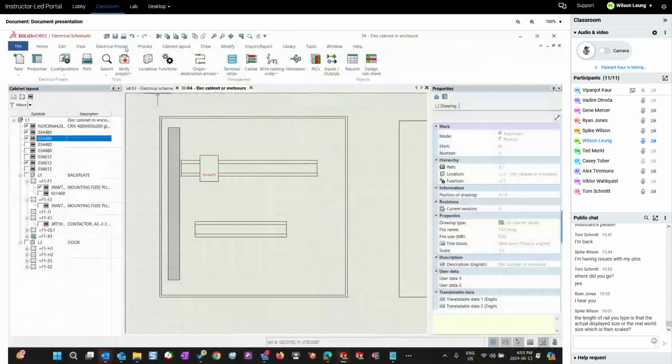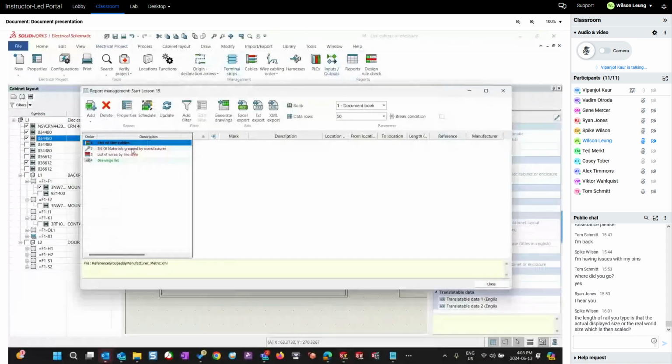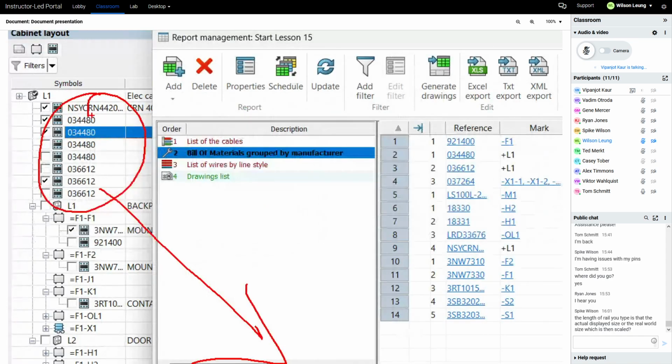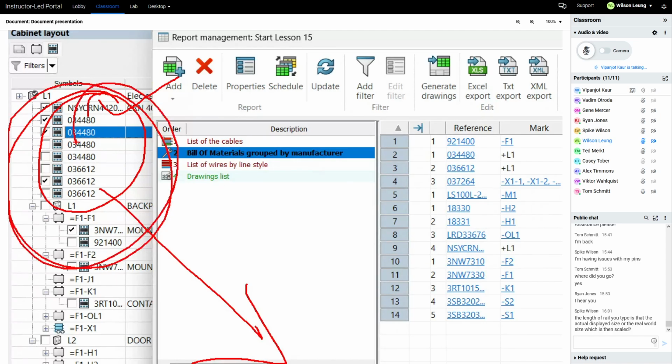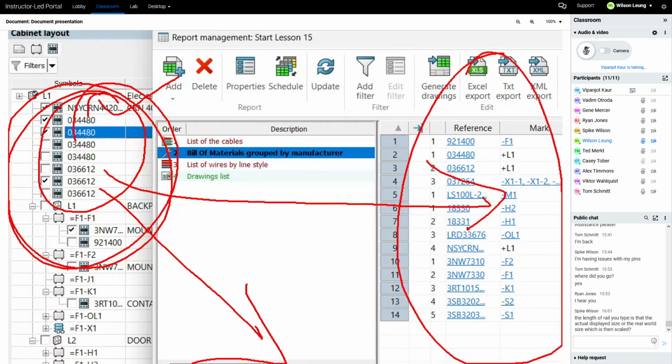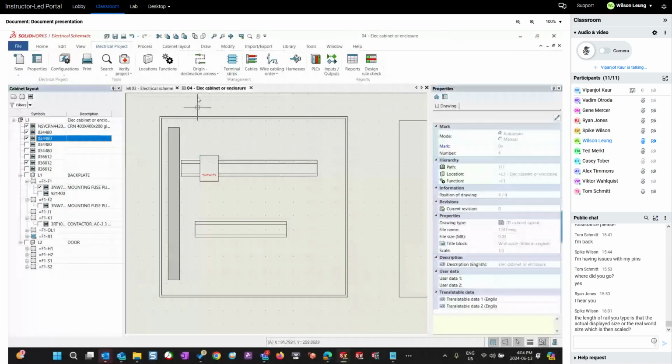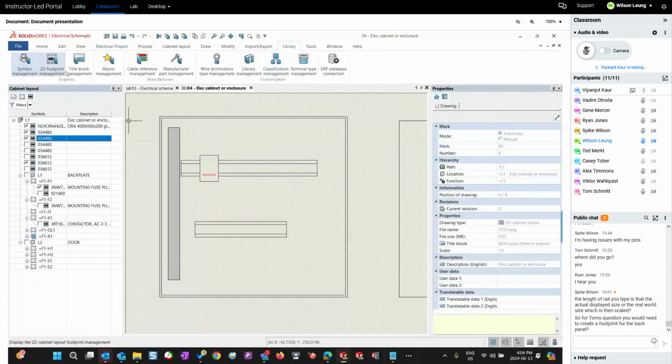And if you add a back panel separately, if you're placing an order for it separately, then yes, you would be adding it manually here, then showing it manually. If you're telling me, VIP, for example, for the door, I'm not placing a separate order for the door. It's coming with the cabinet. So I'm not showing the door separately in this list because anything I see here will show up in my bill of material list. And then Victor's going to say, hey, Tom, the back panel is coming with your cabinet. Why are you ordering it separately? So it's up to you. What do you want? If you want to order it separately, then that component should exist separately in your library in your manufacturer parts manager.